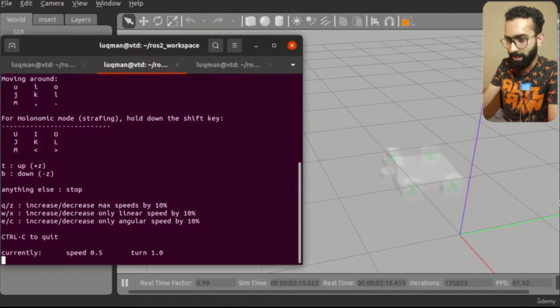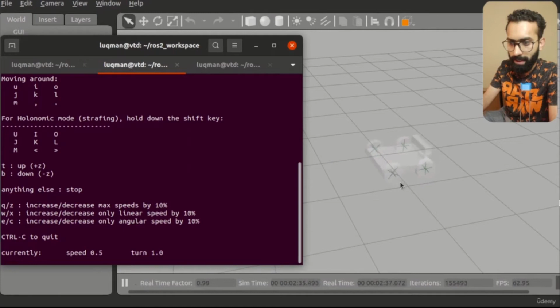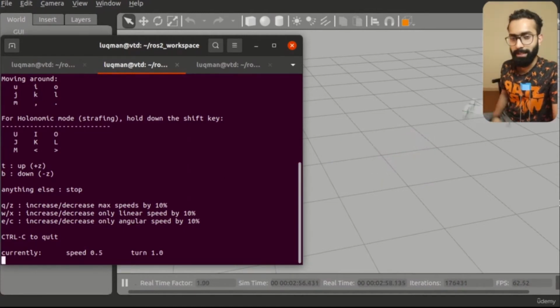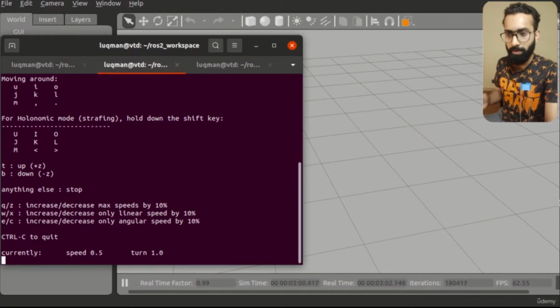Now it is more visible what is actually happening. Okay, now I'm going to stop it. Only this tire is actuated. These front wheels are not actuated, and I want you to actuate them. Currently they are moving because of the inertia, but now when I turn it, only the wheels on the back are producing the motion. You can see the front ones are not moving as these two are moving in opposite directions. If I turn it in the other direction, their rotating direction will change. Very interesting thing about this robot regarding the driving of the robot and the controllers, this libgazebo_ros_control.so file.